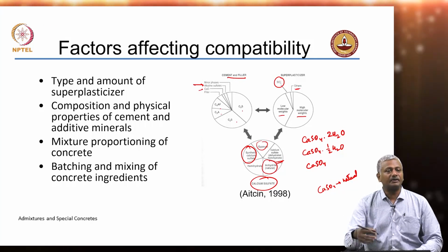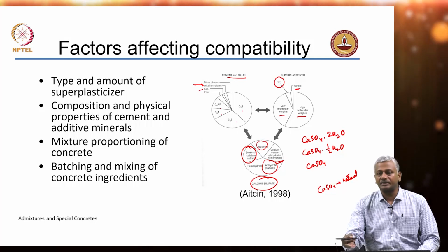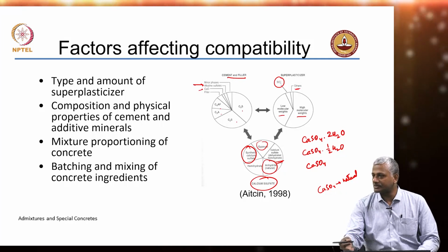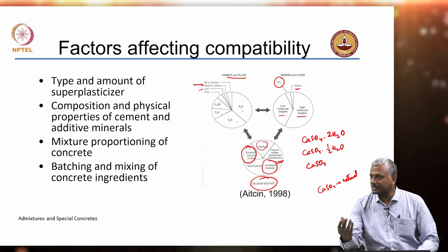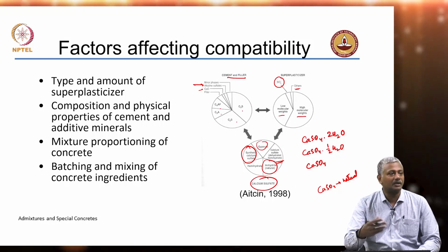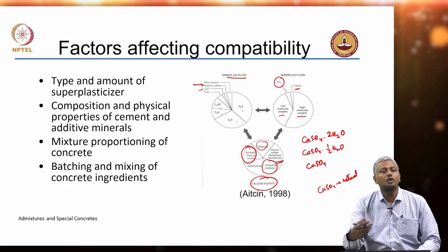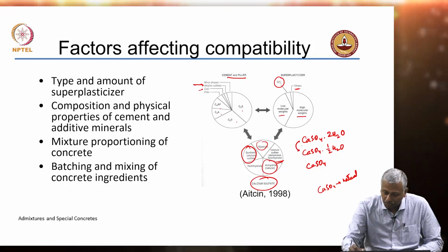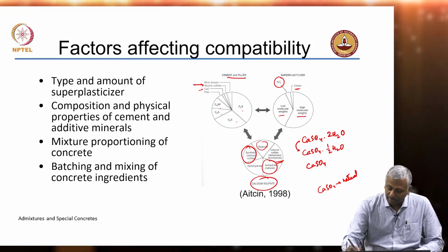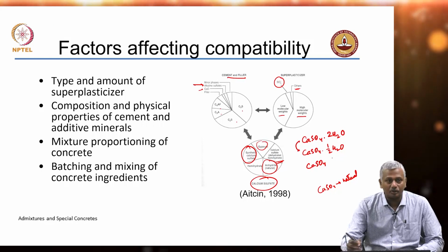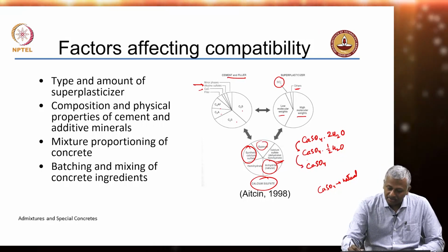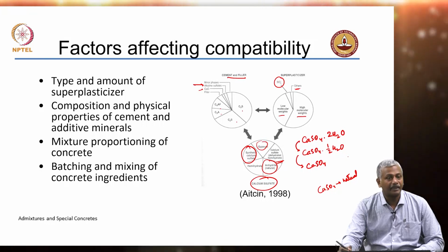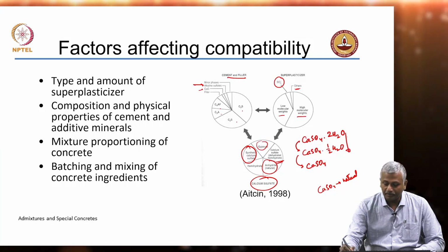It turns out that when you use one or the other of these sulfate species in cement, the rate at which the sulfate becomes available for reaction can vary. Okay. The solubility of the sulfate is different. As you move from gypsum to hemihydrate, or rather synthetic hemihydrate or plaster of Paris, to synthetic calcium sulfate, your solubility increases.